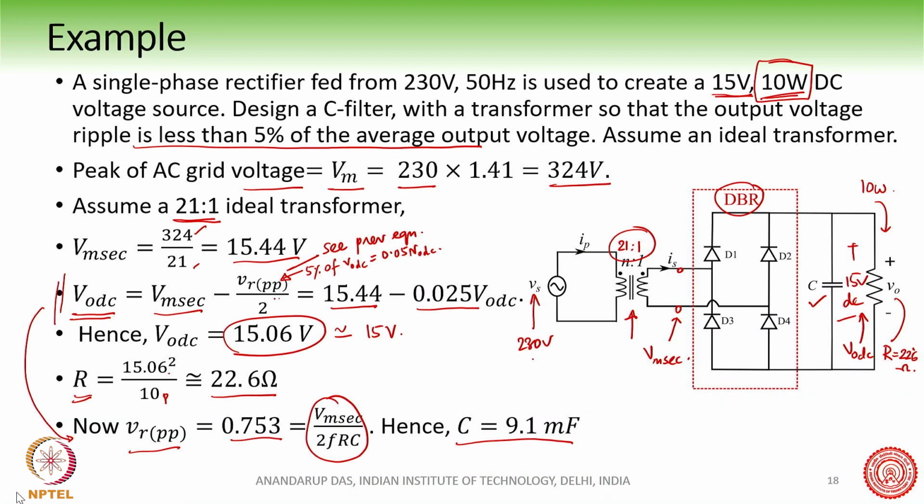In fact, if you see the circuit, it's very simple. A transformer which you can readily buy in the market, diode bridge rectifiers readily available, capacitors readily available, and you can connect them, so you can make your 15-volt power supply.